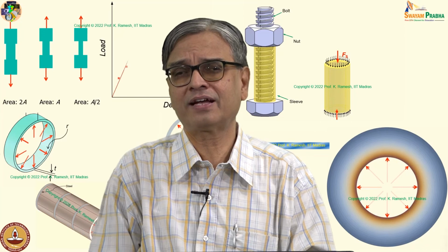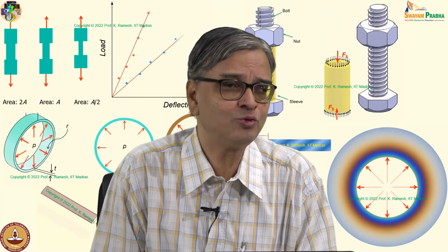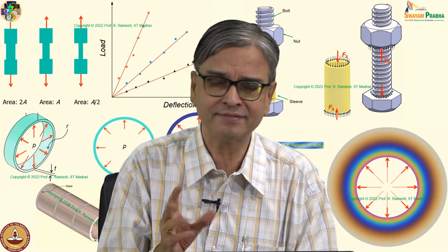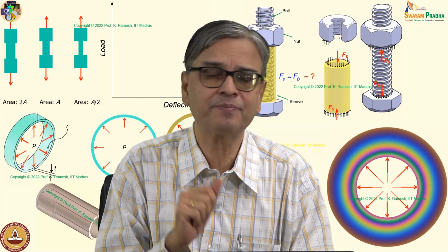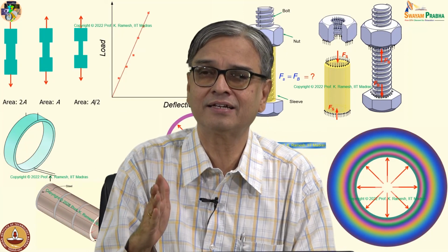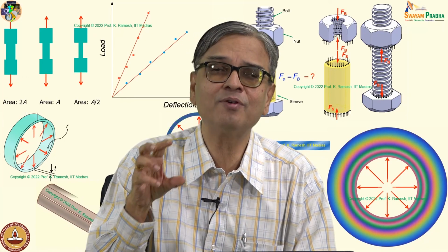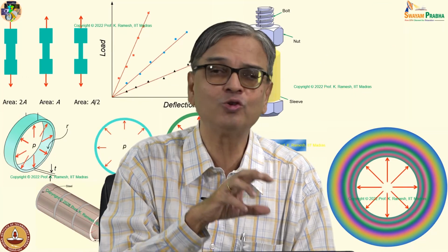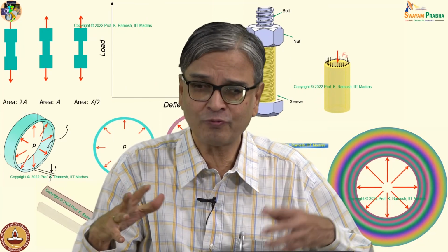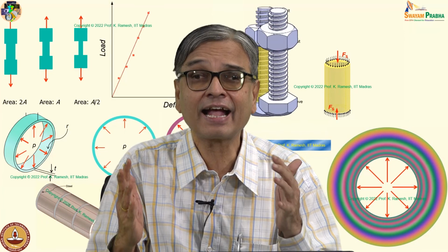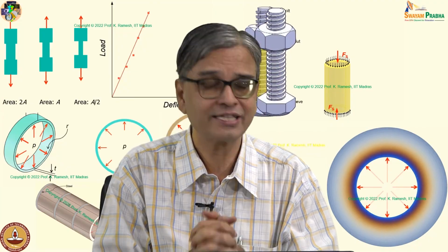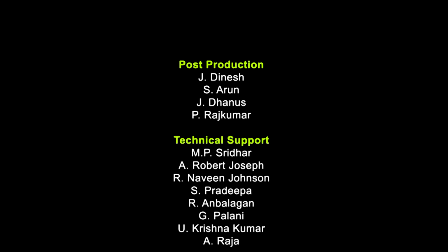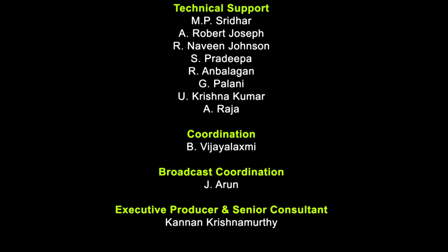And with this we have a bird's eye view of what happens in a thin cylinder, and we have also understood the force deformation relationship. And if you have to handle any new problem, make some of the aspects rigid for you to visualize. From that you find out the interrelationship and carefully write the compatibility condition. You cannot write it arbitrarily. Okay, thank you.